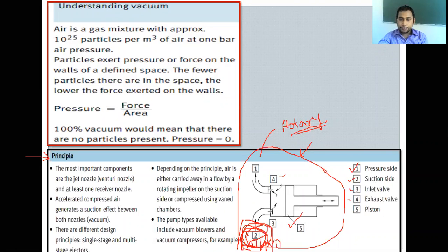It means if we stop the rotary pump and diffusion pump at the same time, simultaneously the 4 and 3 sections are automatically closed down. This part is automatically closed down if we switch off the rotary pump and diffusion pump. Now if we start the rotary pump, the diffusion pump, or the turbo pump,